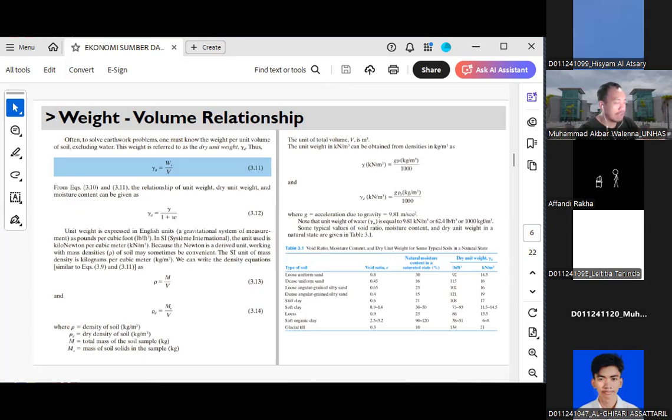As I mentioned before, depending on the permeability, or how quickly water can escape the voids, water can come and go. But the thing that stays constant is the solids. So why it is important is because knowing the dry unit weight gives us a stable reference point for the soil when it doesn't contain water or air.